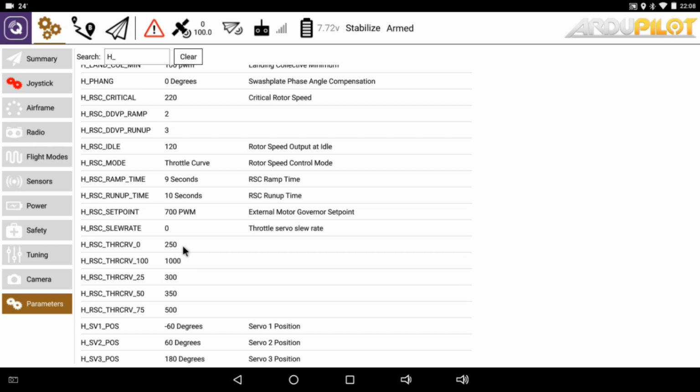You may be flying a turbine engine with a FADEC controller that requires completely different settings, because most turbines will have an idle speed and they don't like to run too much below about 65% torque or they have flame out problems. So if you're flying a combustion engine helicopter, we'll assume that you're probably not a beginner and have a pretty good idea of where to set your throttle curve.